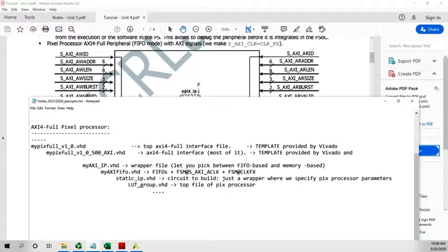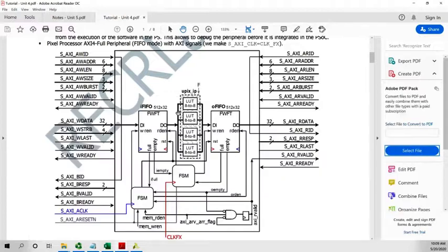and this part is important because we are using a different approach with some significant modifications by me. Okay. Essentially, what I did, as I said to you in the previous lecture, is I included these two FIFOs and I modified the generation of this particular signal. Now, this signal is also controlled by this empty flag of the output FIFO. That is the main difference.